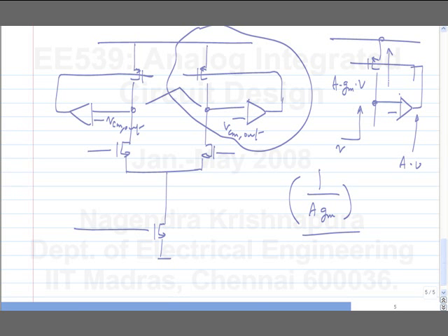So that's what has happened here. You have substituted the load resistances with 0 resistance. So that's why the gain is 0. Not only the differential gain, but each of the voltages individually doesn't fluctuate. Another suggestion is to not use an amplifier, but use a direct connection. 1 over GM. Yeah, that's also not good, right? You need a very large RL of the order of RDS, the order of 1 over GDS. Now we have got of the order of 1 over GM.